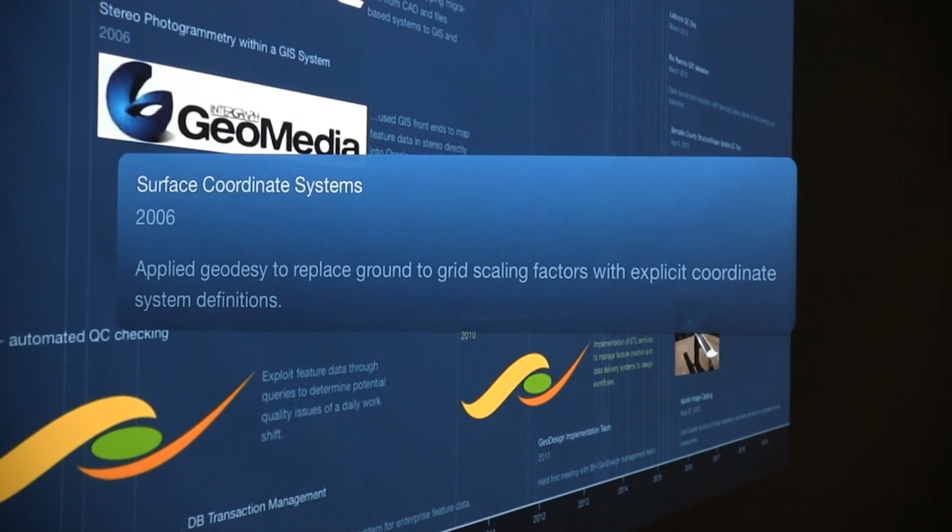So this is important. This is a big milestone in technology for us because we're an integrated company and we work on modified ground coordinate systems, which are not friendly with GIS databases. So we had to figure out how to deal with this in a geodetic way and not just with scale factors. And so this was the beginning of working through that with Alan Benham and others as we had to figure out the Earth mathematics to be able to represent ground coordinate systems in GIS packages.